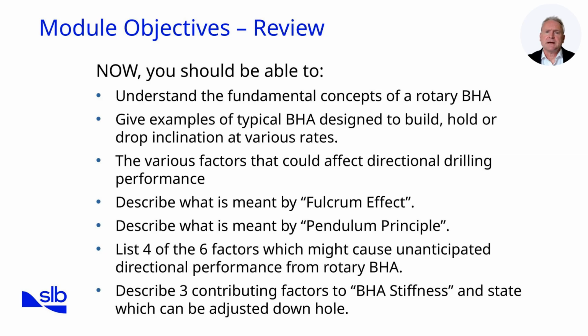Let's review the key learning objectives. By now, you should understand the fundamental concepts of rotary BHAs, including how stabilizer placement, collar stiffness, and gauge conditions influence performance. You should be able to describe the fulcrum and pendulum principles, explaining how they create build or drop tendencies. We've also looked at drilling parameters: weight on bit, RPM, and pump rate, and how they interact with BHA design to influence trajectory.